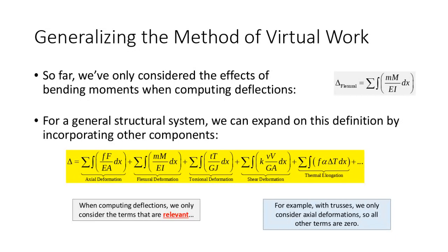Well, torsion, if you're not twisting a member, you don't need to consider that, but if you are, you can plug and chug. Normally in civil engineering, we try to avoid torsion as much as possible. Sometimes it's there, but we avoid it whenever possible. But one thing we haven't talked about is this term right here, the shear deformations. We've never incorporated it in any of our problems. Why is that, and how would you incorporate it?